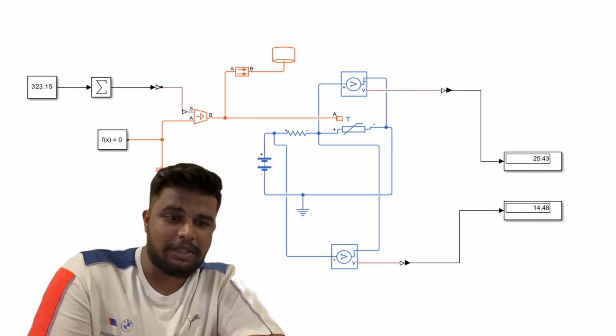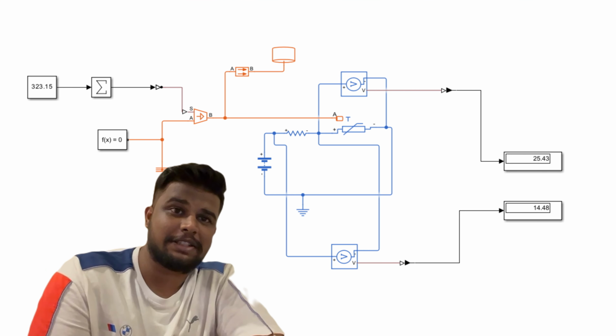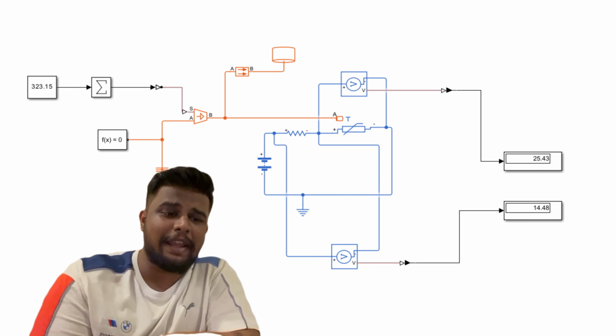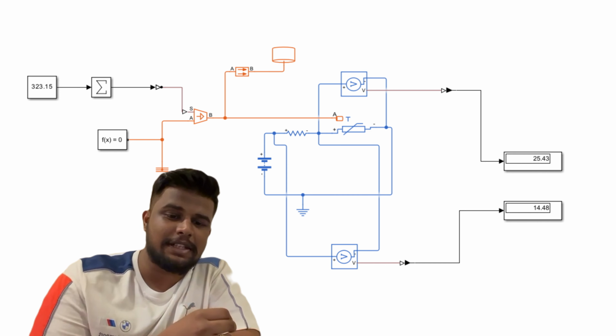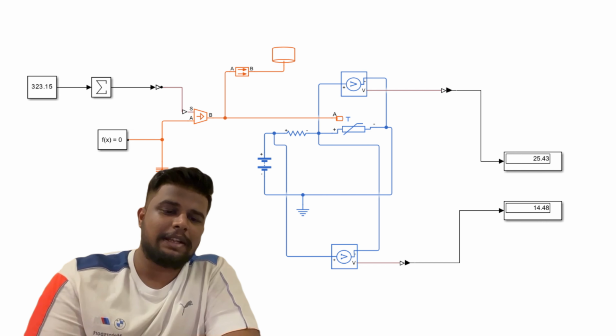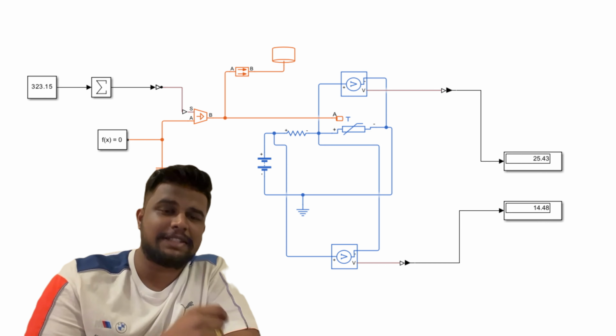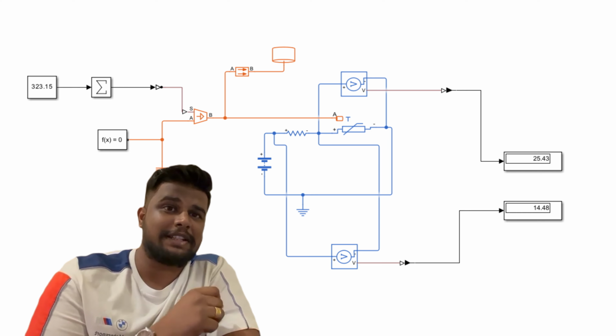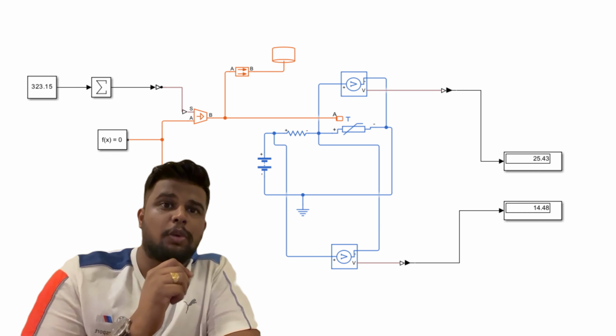I'm excited to present my work on the design and simulation of a MEMS thermal sensor using Simulink. The MEMS thermal sensor specifically detects changes in the temperature and converts these changes into electrical signals that we can measure and analyze. Our design relies on the principle that the resistance of the sensor material changes as the temperature varies. By incorporating the sensor as part of the voltage divider circuit, we can observe how the voltage output shifts